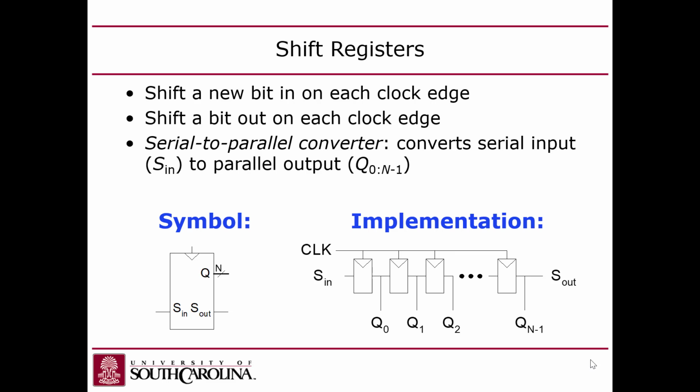So what ends up happening is when the clock edge happens, the data in these flip-flops only shifts down by one position at a time. So in other words, these flip-flops will do a shift by 1 bit every clock cycle, right? So it'll just continuously shift data down.